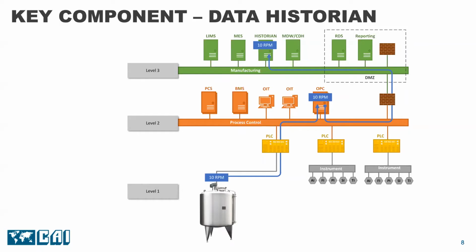A data historian is invaluable and is the basis for almost every one of the analyses listed earlier: electronic production or batch reports, statistical process control, cycle time and downtime statistics, yield calculations, OEE, cross-batch comparison, and golden batch.